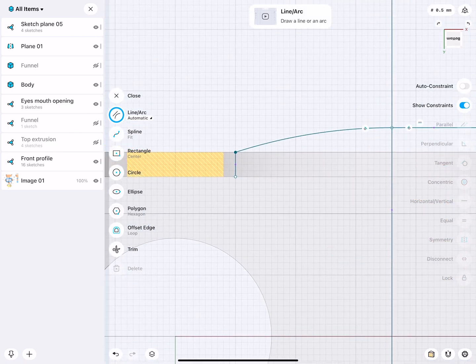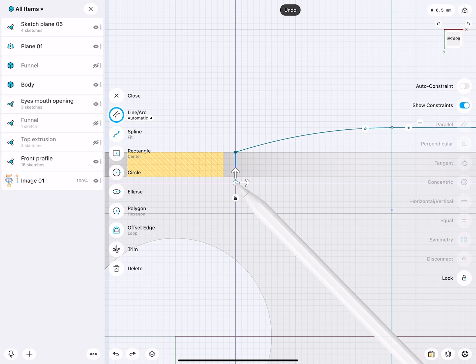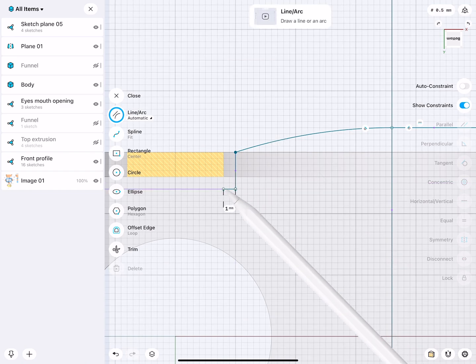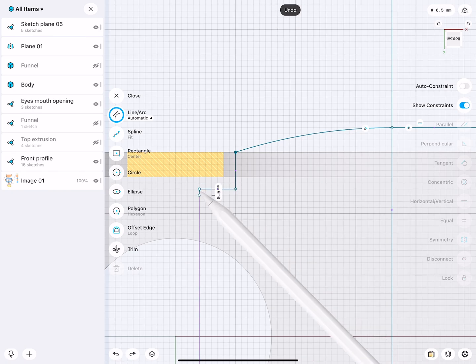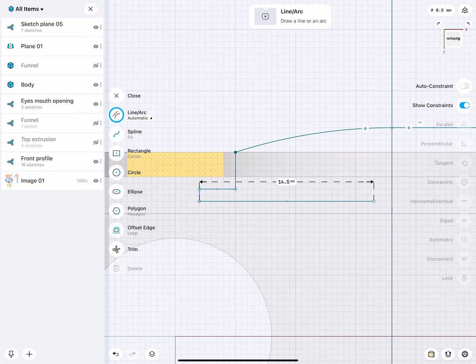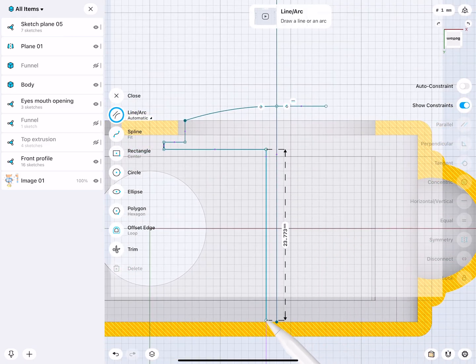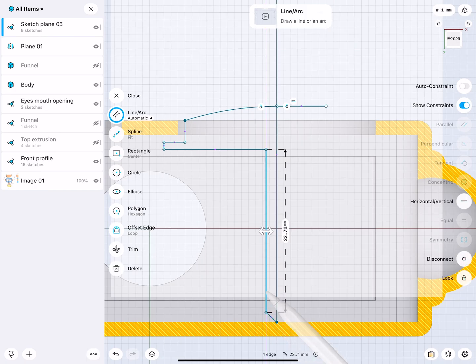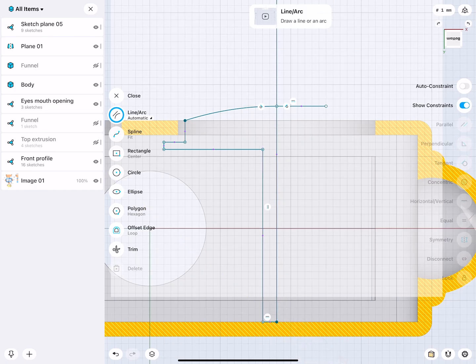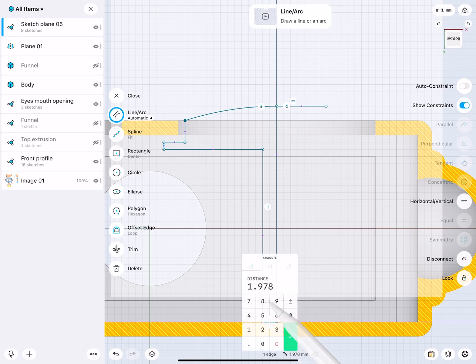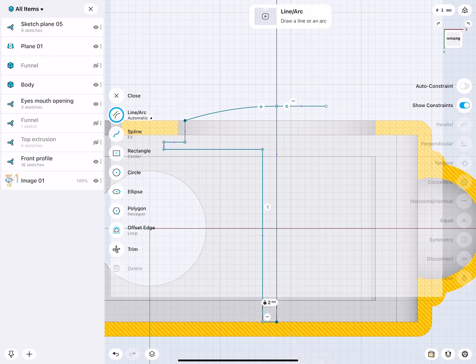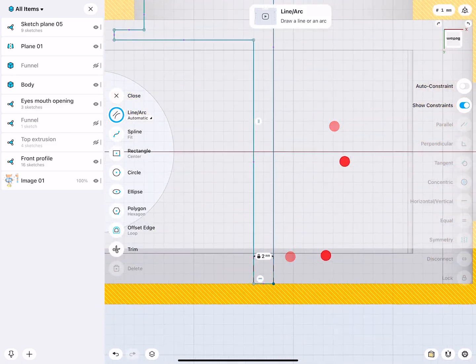The eye should rotate, so it should also be a little bit loose. What's actually this distance? This is 0.5 millimeter, way too small. So a millimeter, we give this a nice loose play. How much is this? 2 millimeter. This is fine, maybe 2 back. Then we draw this over. I'm using the grid simply to line up everything nicely. Bring this one down to there, and then say, hey, all you horizontal, vertical, what is this one? 2 millimeter is good. Very nice.